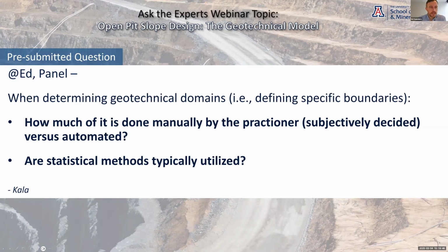Yeah, thanks, Jillian. It's a good question, and I think it probably varies between approaches, but for us, and I'll speak for Andrew as well, a lot of it is done manually, pulling geological data and geotech data into things like Leapfrog, and spinning around your models and looking at changes and patterns. Very important for structures. A stereonet tells you a 2D image, but what does it look like at 500 meters depth? Very different than the poles in a stereonet. So you really have to spend a lot of time manually looking at it.